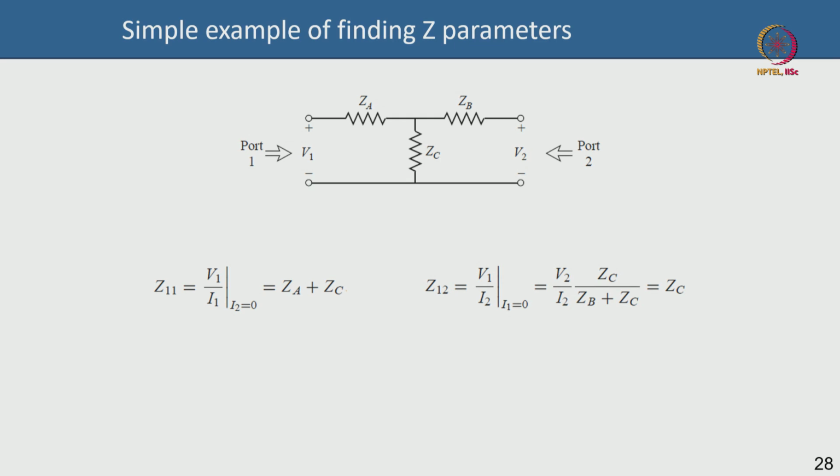You cannot do it with just one matrix. You cannot just have S parameter, it will make it very complicated. You have to convert the measured S parameters into Y or Z parameter and then reconvert to H parameter in order to gain insight into the cutoff frequencies, for instance.